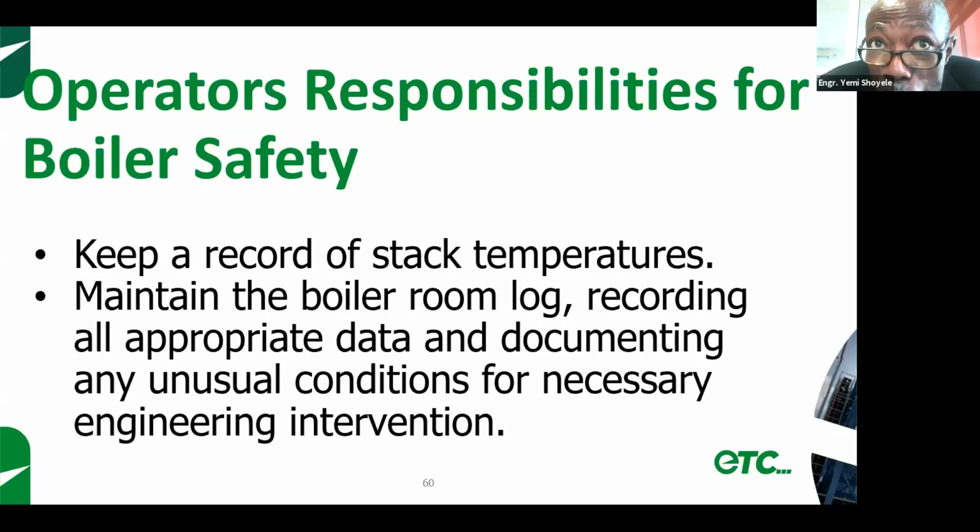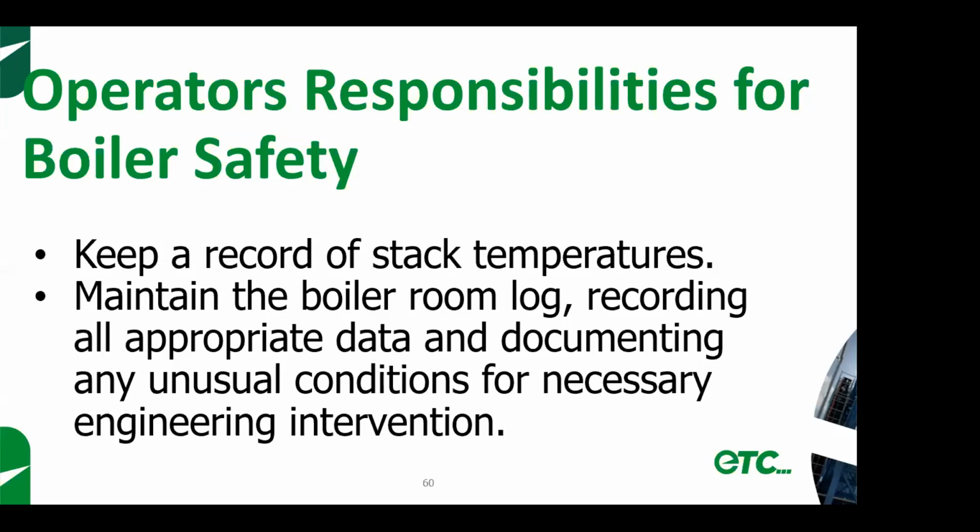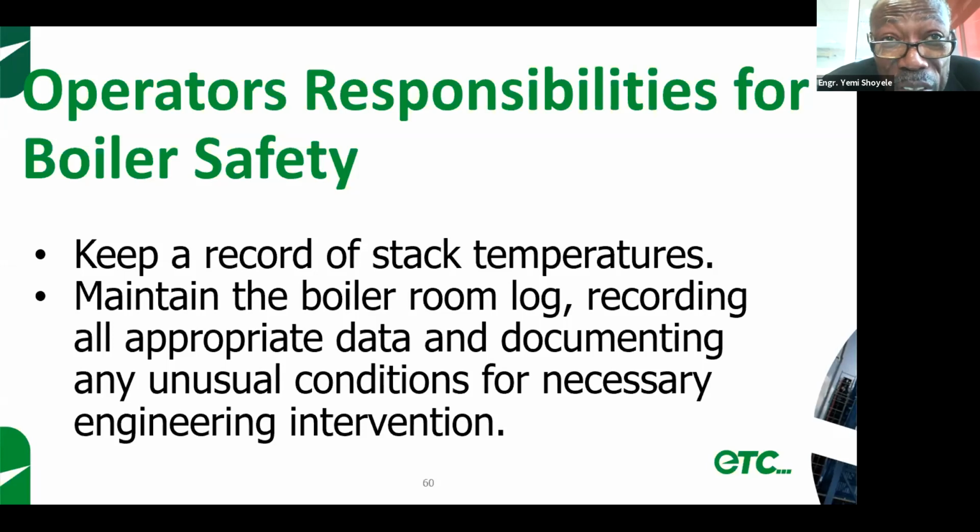One of the main causes of slow pressure buildup, let us assume that your firing rate is okay and you put in enough energy, the flow rate of the gas or the oil is okay. One thing that normally prevents you from firing up, and I've seen this in industries, is low feed water temperature. In the fire tube boilers that we use in most of the manufacturing industries, we have this kind of problem a lot. You must ensure that you have, as close as possible, between 92 and 95 degrees C minimum as your feed water temperature.